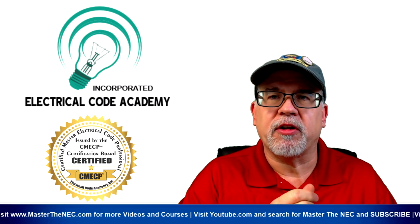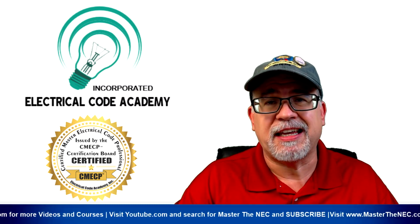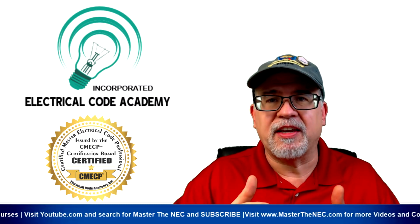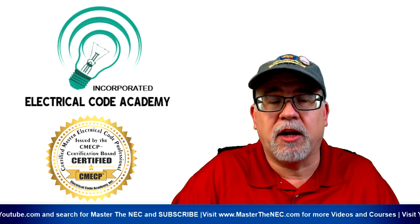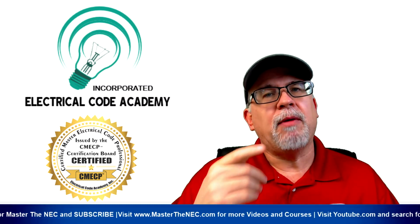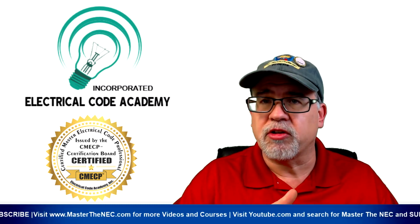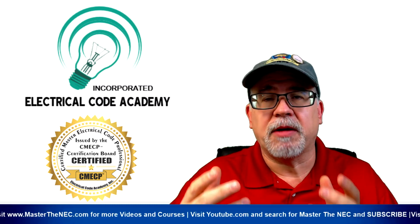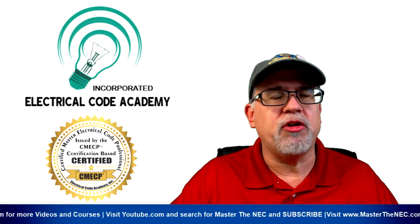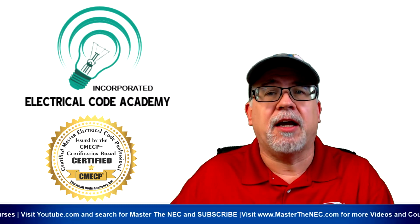A real quick explanation of quad rated is many people are very familiar with plain USE-2 underground service entrance conductors, which is also slangily used as a cable, can be bundled together or twisted together with other conductors and they're put into the ground, okay, under UL 854. Okay, direct burial rated. Gotcha, as long as it has that on the wire. However, that can't come into a building. So maybe that's outside, and then the moment it transitions into a building, like goes into a raceway, it can magically become RHH, RHW-2. So if it does have a USE-2 with multiple ratings on it, then you can rest assured that it's probably got flame retardant properties to it, so it can come into a building inside of a raceway.